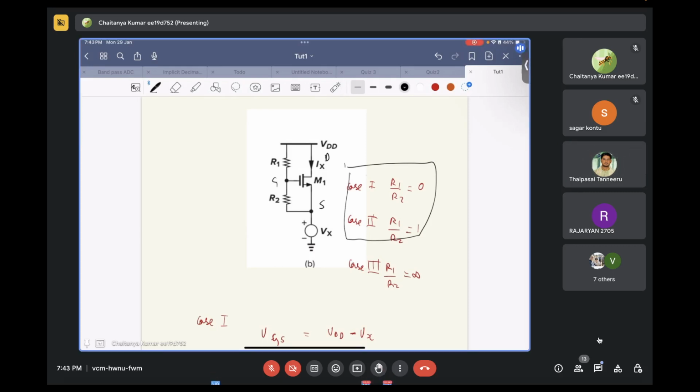Okay, for NMOS, depend on the two statements I gave you, right? For the transistor being in saturation, what is the condition in NMOS? Your drain can go. Yeah, drain should be less than or equal to VG minus VT, sir. Correct, correct. So can that happen?